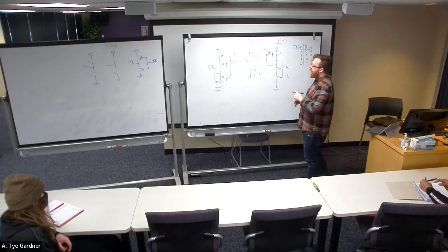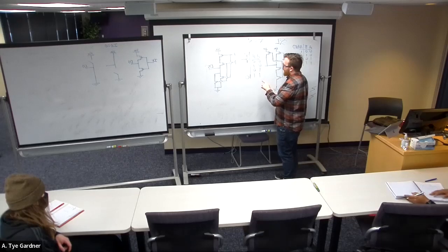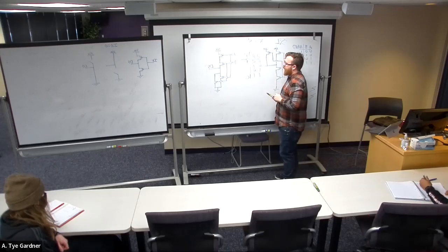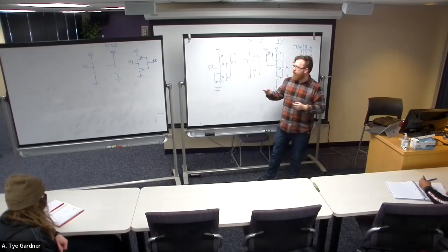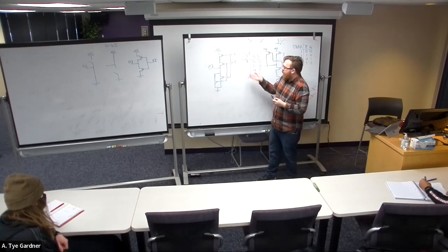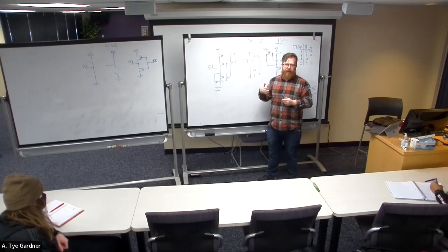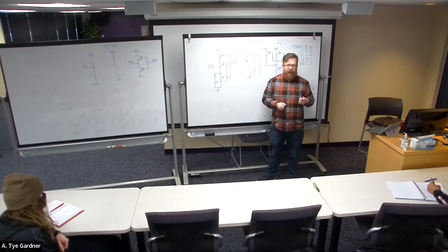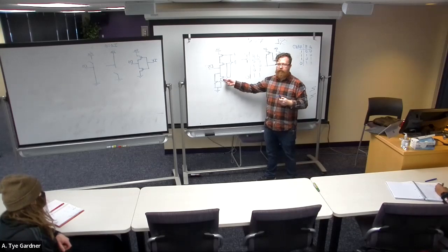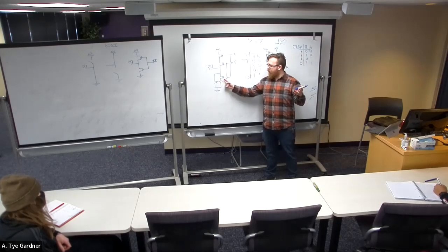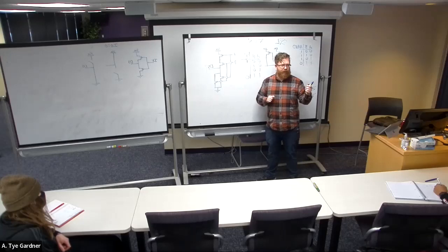Okay. Now let's go look at the 0-1 situations. Well, in this case, the pull-up network is really easy, right? Because if we look at the pull-up, if either one of them is 1, then the PMOS device turns off. It doesn't connect and it cannot be 1. And then if it is 1, then the NMOS does connect, it does turn on, closes that switch, and it connects to ground. And if either one of those does that, it is 0.